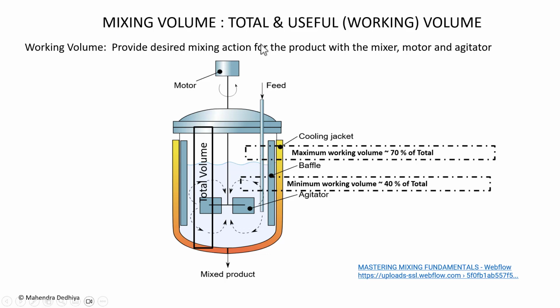In addition to that, motor, gear, and power are extremely important. And engineers will be involved in advising on the power consumption. If the viscosity is high, it will require more power to move the liquid. All these things need to be understood by formulation development scientists when you are developing a lab scale batch. And commercial scale batches can be larger scale, in thousands of liters.